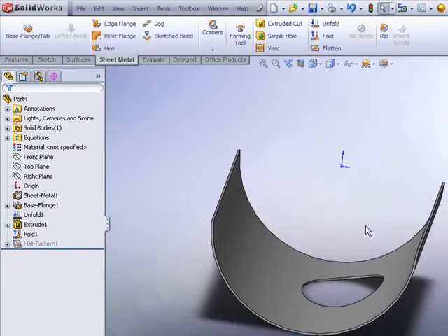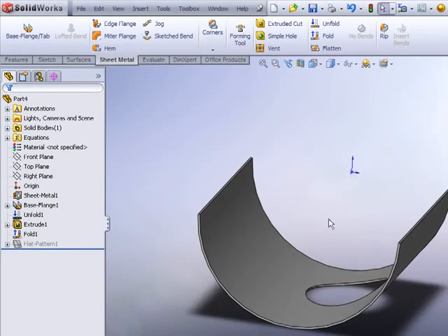So begin your rolled sheet metal parts by designing them in the rolled state, and then just use the unfold and fold features to build in any features that would normally be defined with respect to the flattened state.